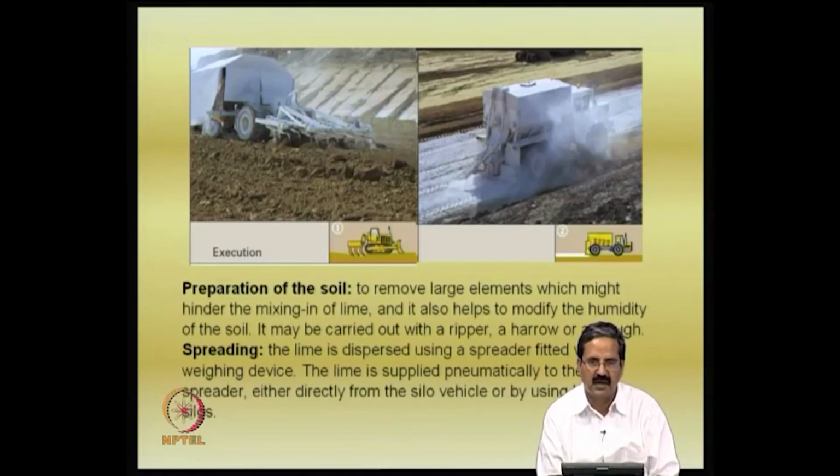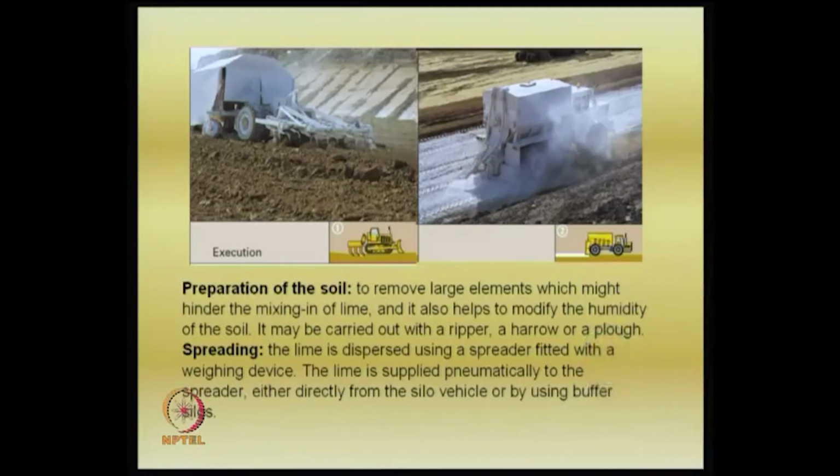In fact, I just mentioned in the beginning that the type of soil has an influence in controlling the volume change, and also the type of clay minerals. So, for example, if you take a clay of high plasticity, lime will have a very good effect, whereas if you take a low plasticity soil, it will not have that much effect. So with this, the clay mineral is also another important result which has been brought out very well